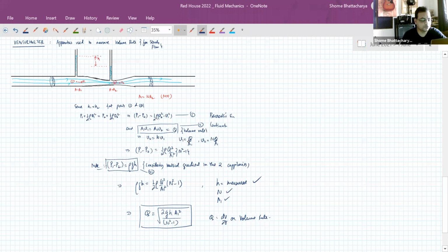So of course, if the velocity of liquid flow becomes too large or the volume rate becomes too large, then we lose the property of steady flow, and there is what we call turbulence. And later in properties of matter, we'll see there's a calculation of something called Reynolds number for the flow. So the Reynolds number's value tells us whether or not we can get away with applying the steady flow motion concepts, or turbulence is becoming too strong a factor for our analysis to be correct.